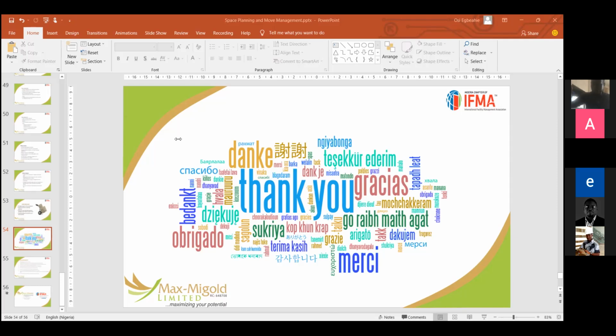Okay, I'll put it this way. The question you asked is actually vague, because normally when we're doing space planning, we treat it per space. The number of persons that normally will be in a space will determine the level of artificial ventilation you need to provide. For artificial ventilation, you use the air conditioning system, which gives you the tonnage of the air conditioners that you use. The size of the space and the number of people that will be in that space will determine the tonnage of the air conditioning unit you use. Whether you use a 5 horsepower, 10 horsepower, or thereabout, you can then decide to either have one or spread it into different units.